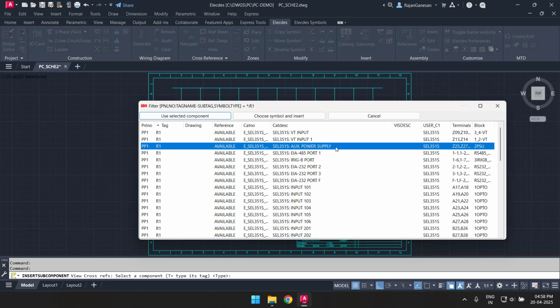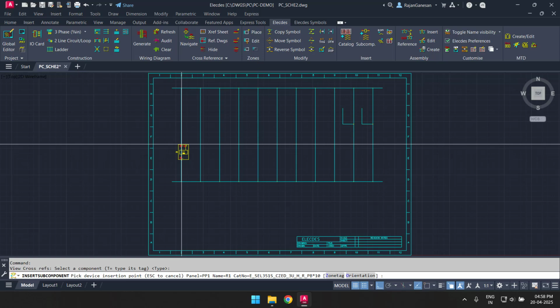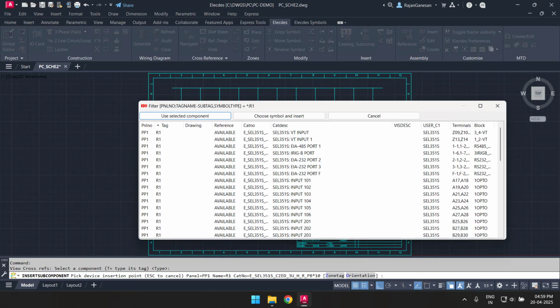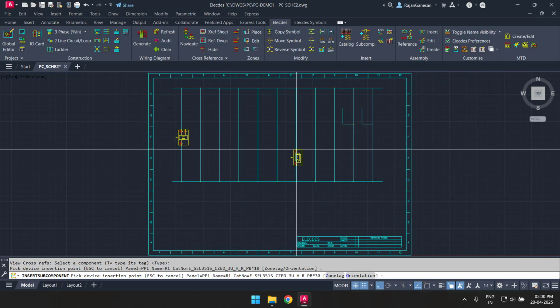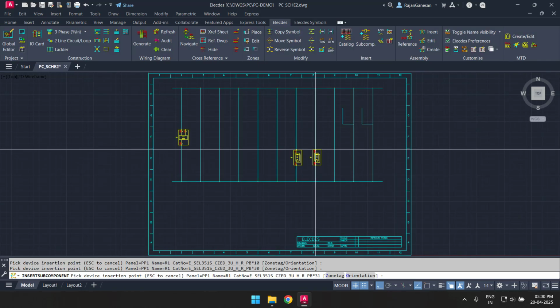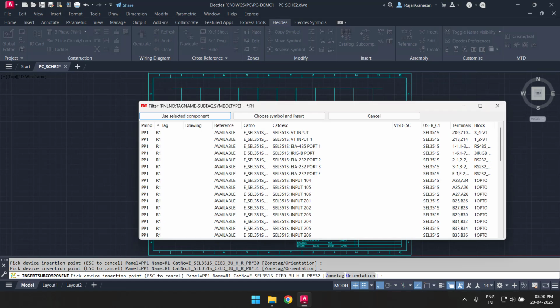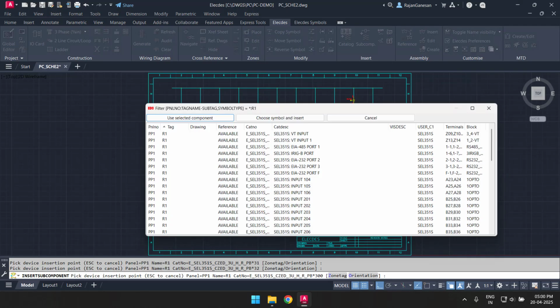I will firstly place the relay's auxiliary power supply onto my ladder. Now I will insert 3 opto inputs from the relay. As the symbols are inserted, they become unavailable for further insertion. This ensures no duplications occur. The terminals and ratings, such as input status or output function, are managed, saving a significant amount of production time and rework.